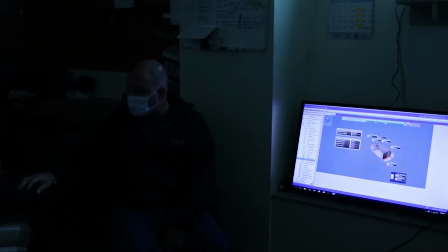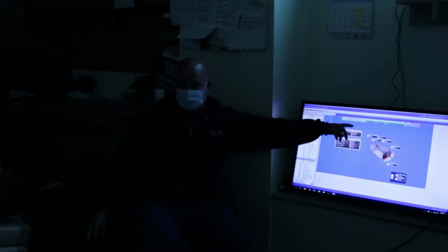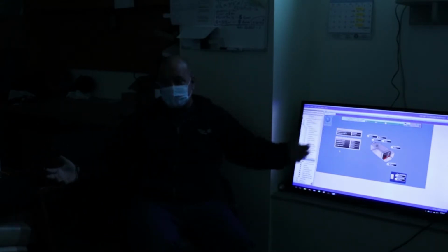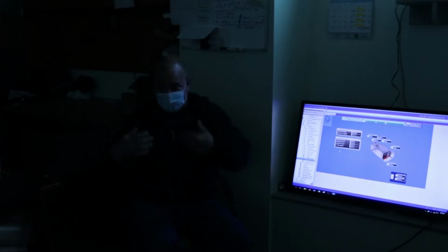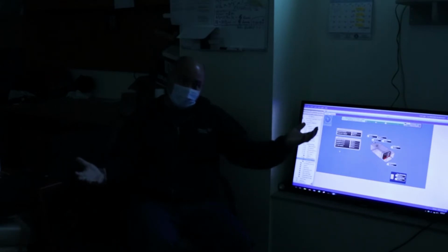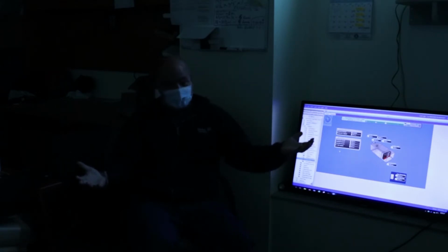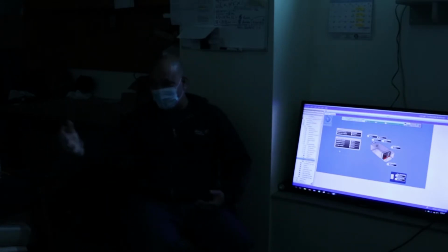We can't make everybody absolutely happy. When you look at the VAV box, it'll tell you the rooms that it feeds. When you see multiple rooms, you know you're probably going to have a problem. The only way to handle it is to make an adjustment that affects all three rooms. Chances are you're only going to know about the person that's complaining, not the person that's satisfied. After you make the adjustment, the person that was satisfied is going to complain.